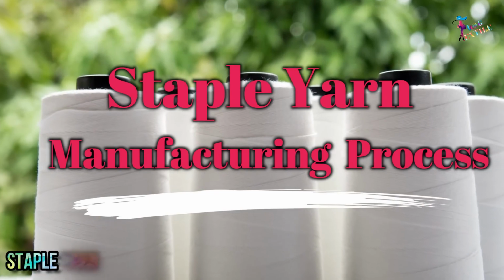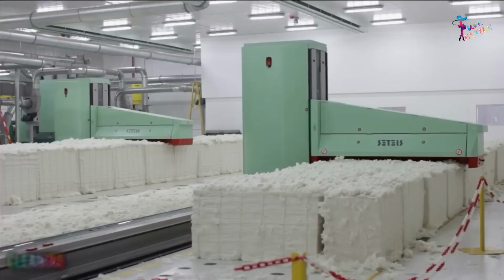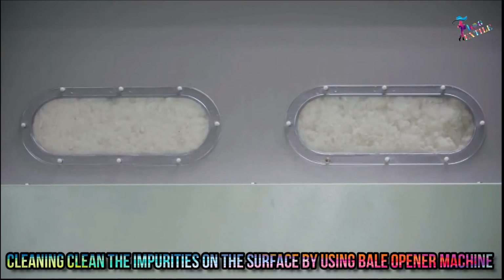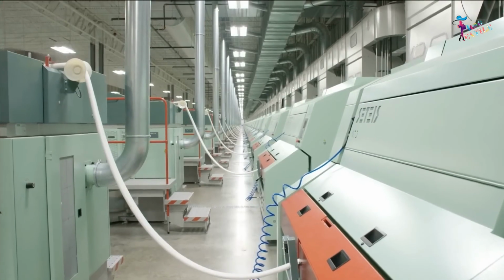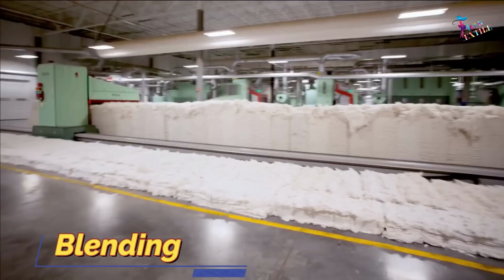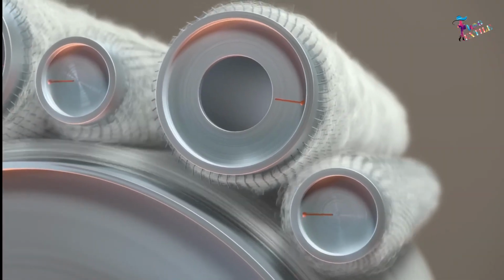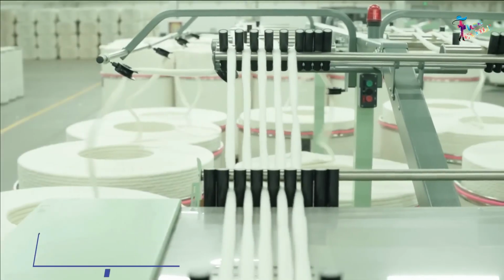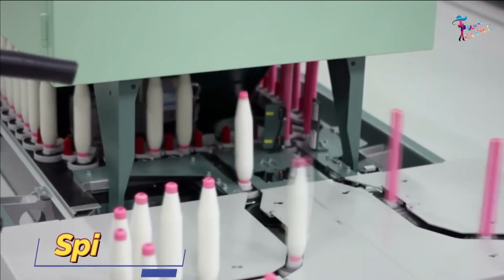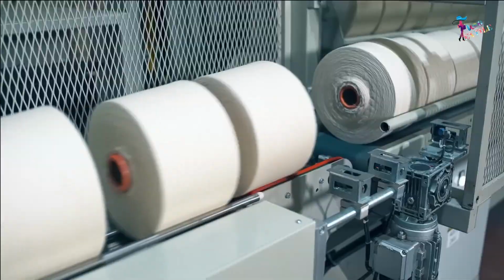The process of staple yarn manufacturing starts with opening the bale of fiber and cleaning the impurities on the surface by using a bale opener machine. Then the process is followed by a series of continuous operations such as blending, mixing, carding, drawing, roving, and spinning. And finally, we get the cones of yarn, which is used to make fabric.